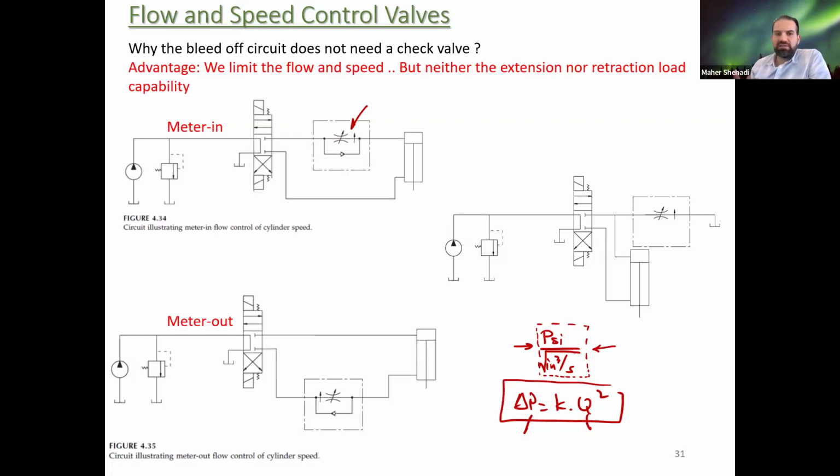We did solve some problems where you have a follow-up part where they would say, what happens if now the speed of the piston or the motor needs to be adjusted to half, to 10%, and so on. And you need to use that valve in part B. So if you calculate K in this unit, make sure you keep it in this unit, and you have Q in cubic inch per second in the second part.